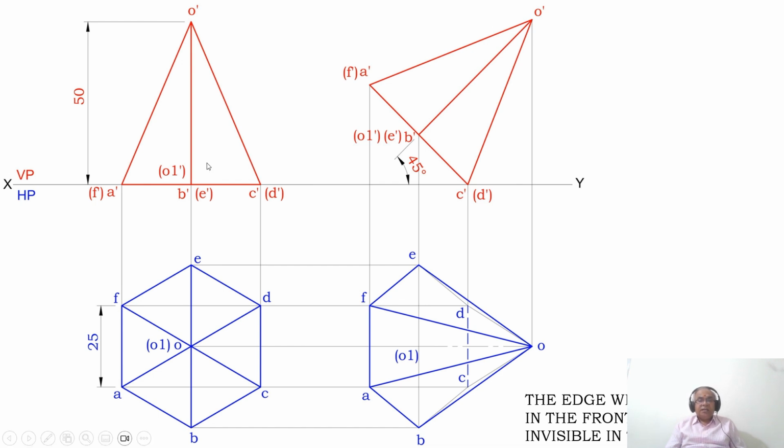As we know, AF, AO and FO are the slant edges which pass across this base edge CD, so that will automatically become invisible, because visible and invisible edges can never cross each other. Applying that condition also you can check whether this line is visible or not. Yes, it is invisible, because the visible edges AO and FO are crossing this edge. So this is how you write the second position top view.